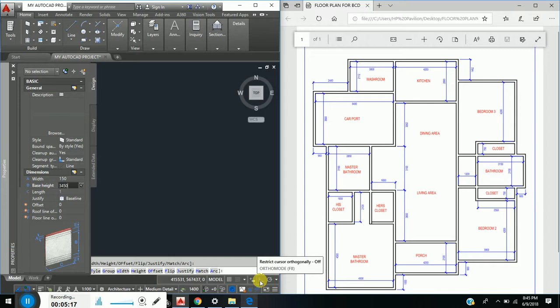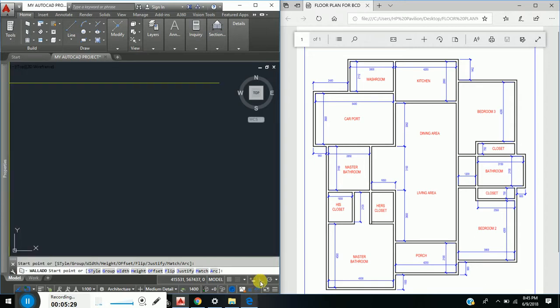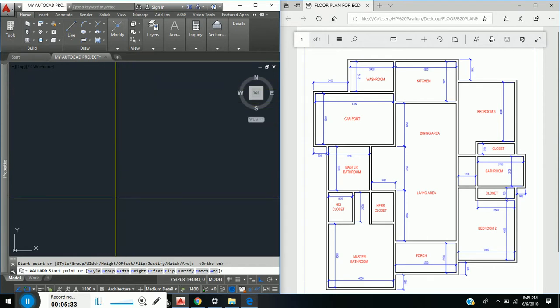With that done, we ensure that our auto mode is on, because we would want our walls to be moving either perfectly vertical or perfectly horizontal as displayed on our diagram. So we turn our auto mode on. And on our screen, we pull down and to the right, because the first wall I'm going to be drawing represents this wall here along with this wall.